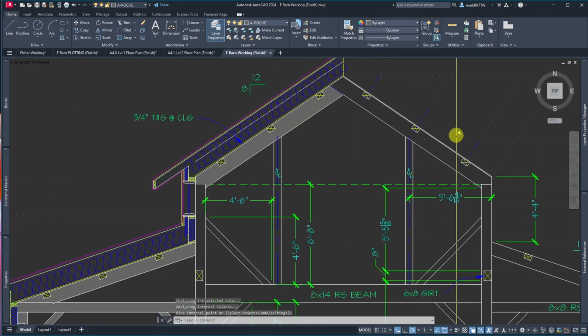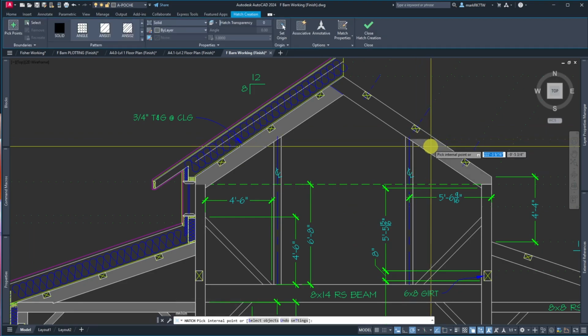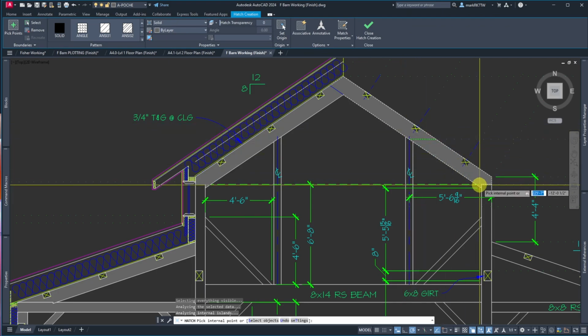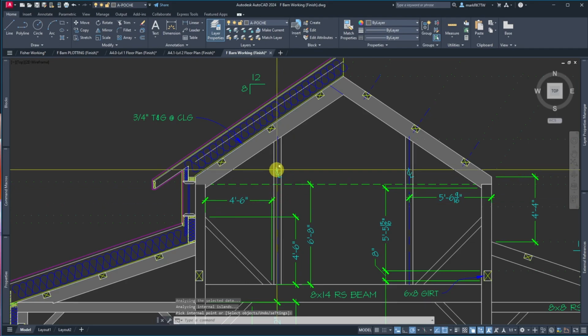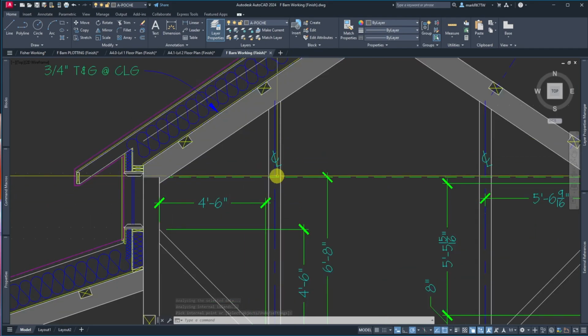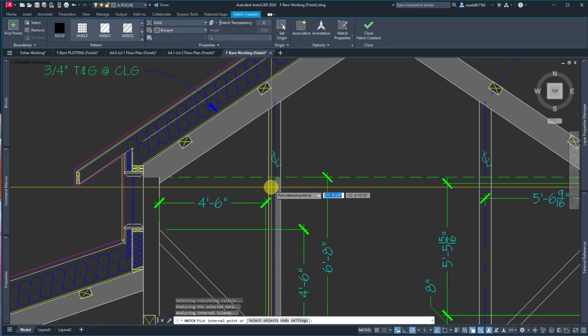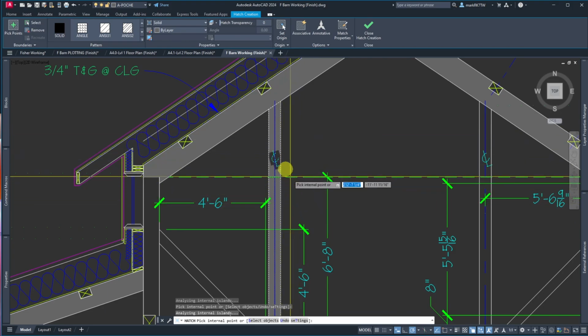The same deal over here, and we've got a break in a line right there. So I'm going to hatch. It's going to grab that portion, then this portion, and then our little tiny guy. So those are hatched. Now, what's nice about text is that it will hollow it out, but you're going to see something not hollow out very well here. Hatch, click, click, click, click. Oh, it did a nice job.